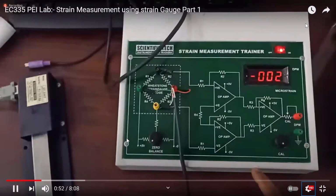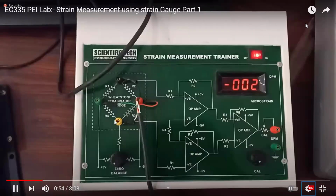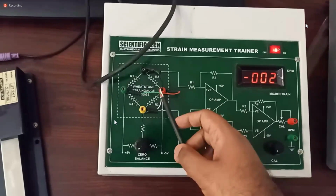Here, the strain gauge is connected as one of the resistors of these 4 resistors. Initially, before applying the load, the 4 resistors are the same value, so the electrical output will be 0. But we are applying load on the strain gauge, so resistance will vary. So we will get different outputs. You can see the circuit of the instrument. The strain gauge is connected as a Wheatstone bridge. That voltage, which we need to measure, that is the strain, is amplified using this instrument that is being used to measure our strain.